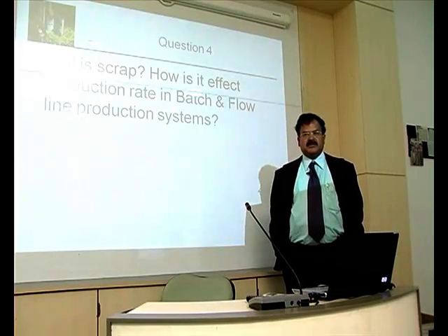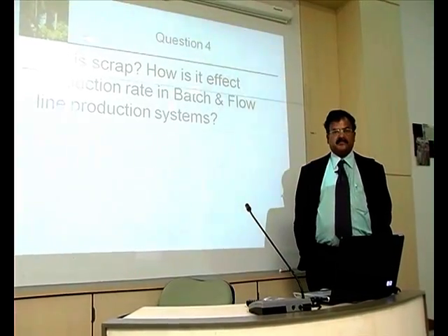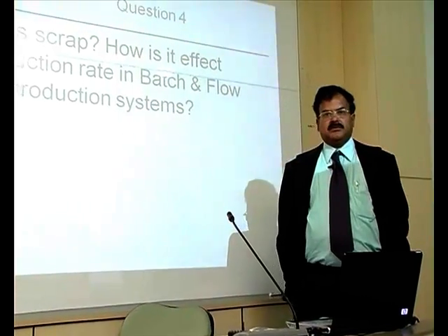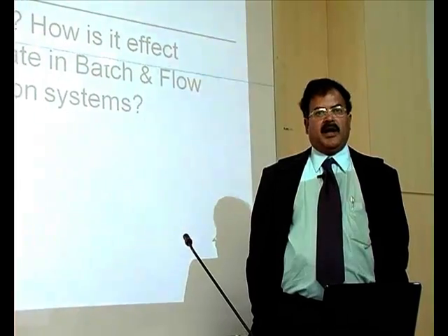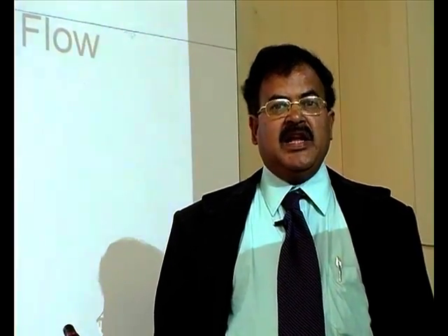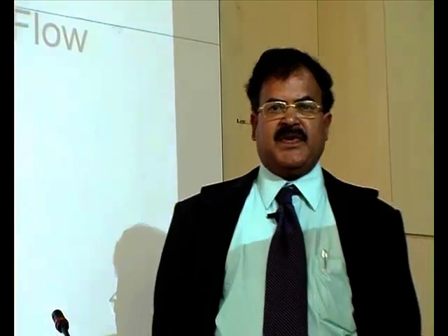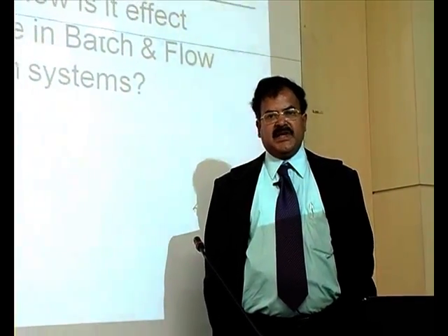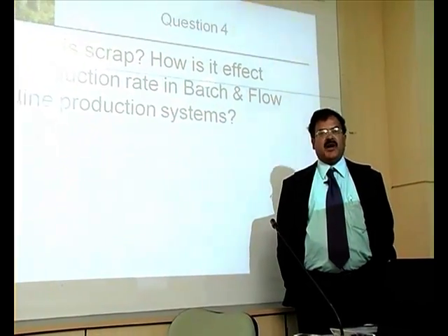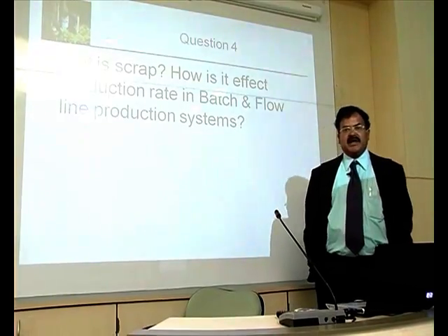We all know that scrap, sometimes we call any waste scrap. Similarly, when you launch a product, it has to undergo a lot of processes. A raw material is taken and it is kept in a first machine to get 1, 2, 3 operations, let us say. When any operation goes wrong due to various reasons, because of the mistake of the human operator or location errors or anything, the kind of tolerances or the required specifications we don't achieve. Hence, this particular part will not function as an original part in the field. Hence, it has to be considered as waste.